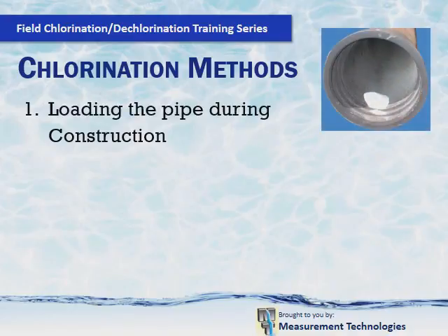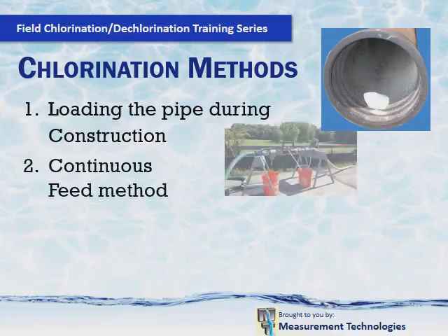With the newly revised chlorination standard, the days of loading the pipe up with chlorine during construction is over, if not limited severely. The reason for this is the increase in flushing requirements and the awareness of the harm that chlorinated water has on the environment. We have seen over the years the method of loading the pipe with calcium hypochlorite during installation of the pipelines to now having to use other methods. The reason high volume flushing has increased.